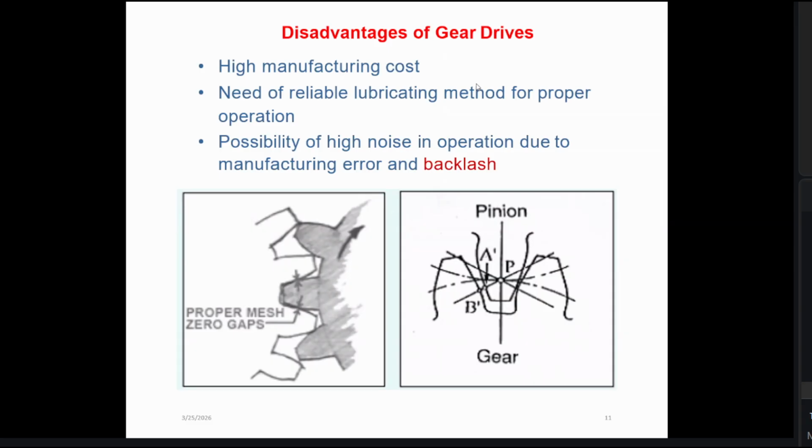The method is also a bit weird, but we can manufacture, but we don't recommend a lathe machine. Sometimes based on the material properties we can use it, but casting, EDM wire cut, CNC milling or conventional milling is the recommended method for gear manufacture, right?